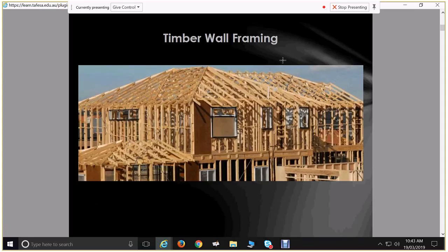So that's our timber frame. This one's a two-story. It appears to have a conventionally pitched roof. I can't see any nail plates in there, so conventionally pitched roof. We've got loads happening in that roof onto walls that are transferred to floors. So we've got a suspended timber floor here, with floor joists running through, and then we've got loads imposed through other internal walls down to the concrete slab.